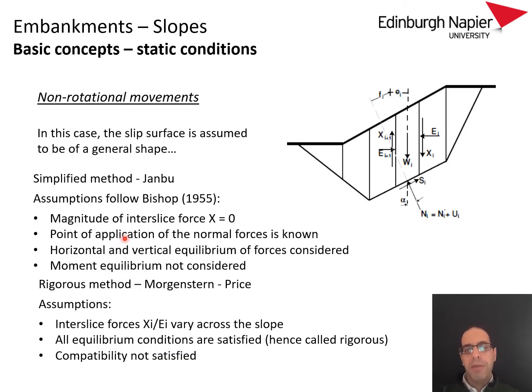What I also said last year is that those circular movements and the assumptions actually apply to non-rotational movements too. You can divide any shape of failure surface or any failure mechanism still in vertical slices, and the Swedish method's equation will be the same when you do the mathematical development, and that's what makes them so popular.